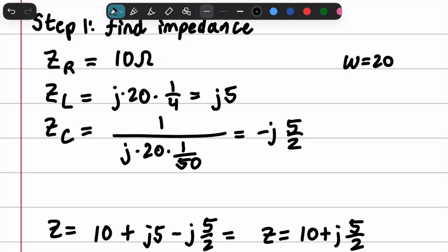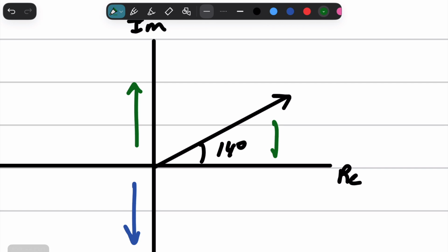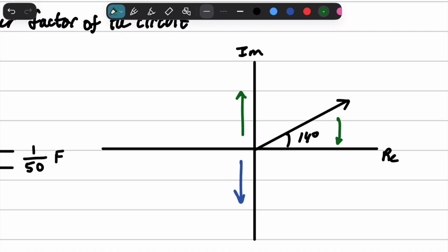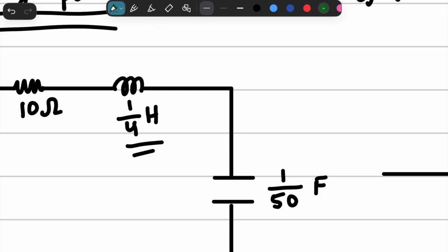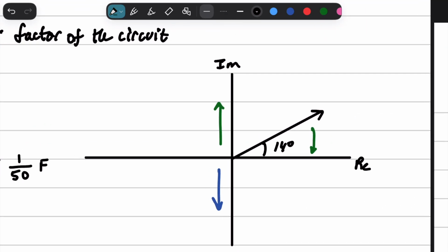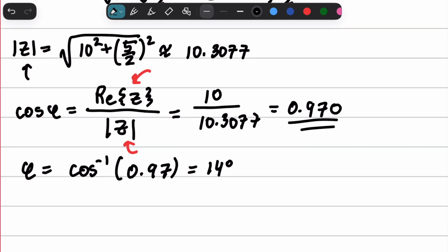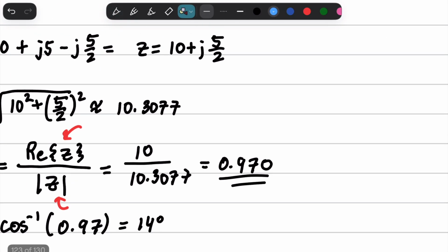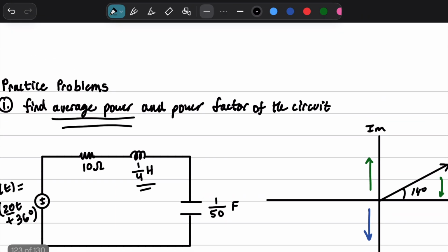And so it's less, right? It's half of that. So it's going to be a little more inductive. But the idea is you want to try to get it down to just the resistor removing power. You ideally don't want these guys to be fighting each other, okay? And so that's what this graph looks like. And so we found the power factor, so that's actually the second part of this problem done, which I should have probably written in an order that you're going to need them.